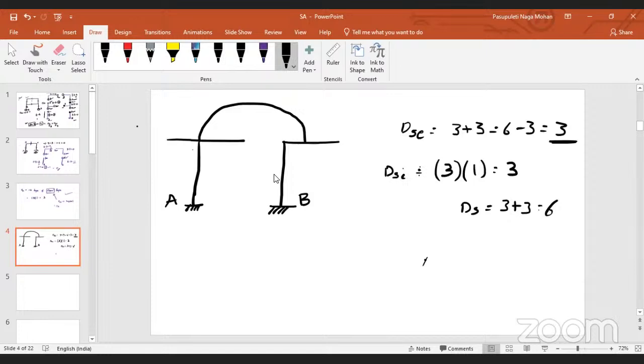But can you visualize the things? Visualization means, let us say I take this C, T, E. Now look at the joint C. How many members are connected there? 4, sir. Now, if I separate them at the joint, at this point how many reactions, how many internal forces will exist? 3. At this point, 3. At this point, 3. Isn't it? Yes, sir. Tell me how can I find all these things?